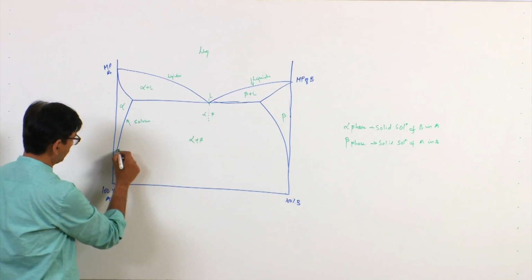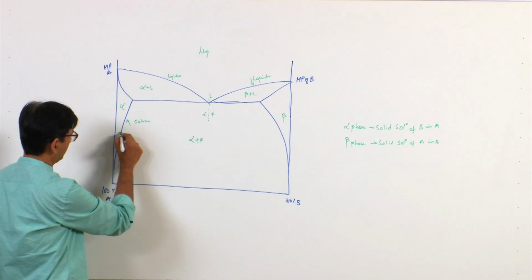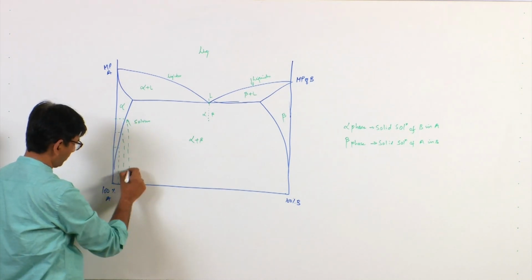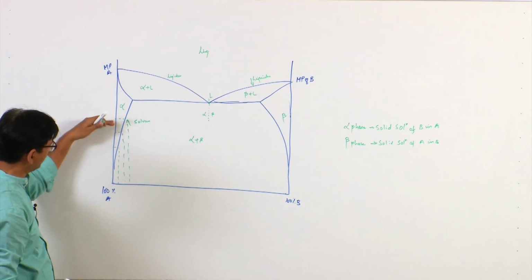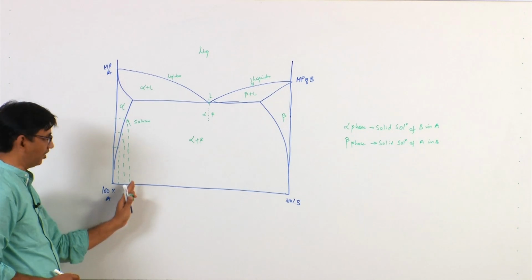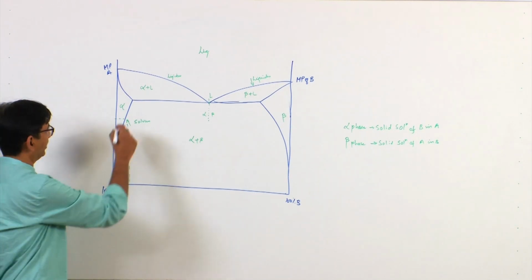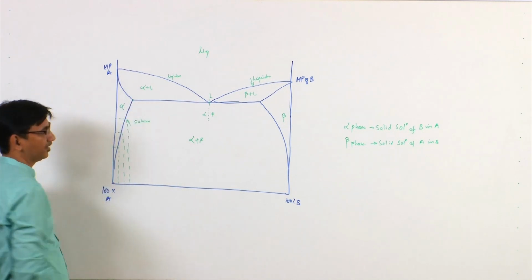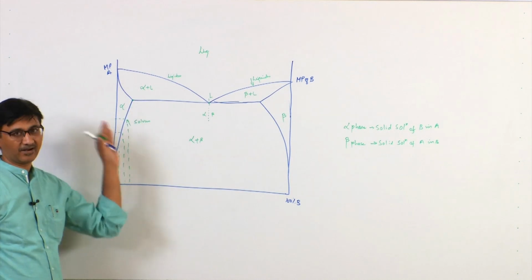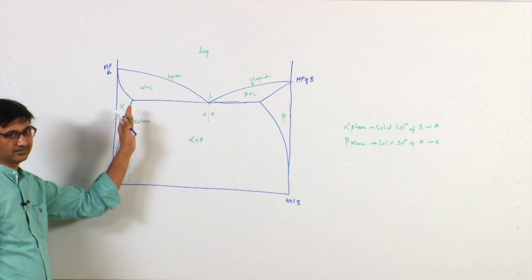So, as you can see, at different temperatures the solubilities are different. Okay, as I am increasing the temperature, the solubility of B in A is increasing. Now, at higher temperature I can have more solubility of B in A, and the maximum solubility will be given by this point; this is the maximum solubility of B in A, I cannot have more than this.